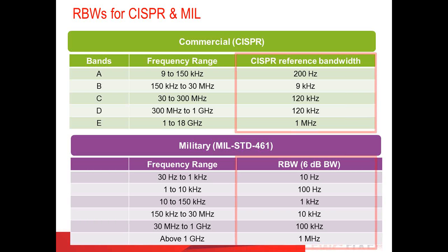You can see that in Figure A. But as you decrease it more and more, and you get to a point where only one of those tones fits within the RBW, all of a sudden you can tell that there are two signals. That's in Figure C. So smaller resolution bandwidth gives better frequency resolution and a better noise floor, but the trade-off is slower sweep time.